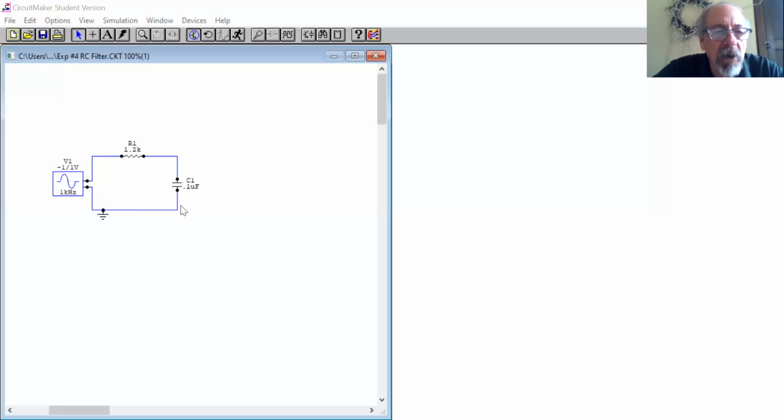The other thing we should talk about is the fact that when I have resistance and reactance in a circuit, I get impedance. The combination of those two things, resistance and reactance, is impedance. And if we use Ohm's law with impedance, the series circuit here will be the reactance of this capacitor divided by the impedance of these two elements combined together.